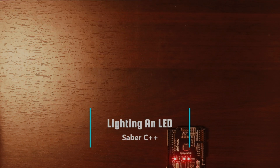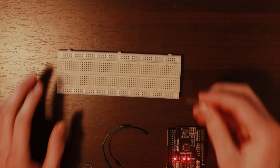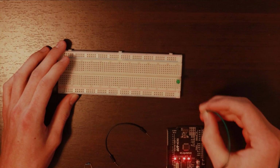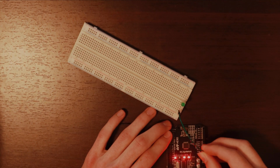Let's take a look at lighting up LEDs with our Arduino. We'll need our Arduino board, a breadboard, an LED, a couple of jumper cables, and a resistor. First, let's connect our LED to the breadboard, taking note of which leg is longer, as this is the positive side. Next, let's connect a wire from that positive side to the 5-volt pin on our Arduino.